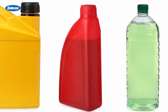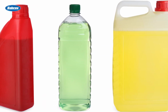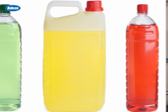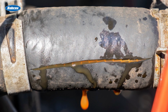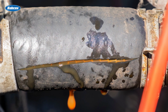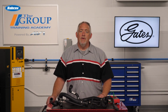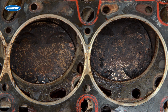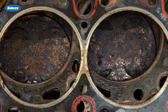Oil and other petroleum-based products are another common cause of these failures. Even EPDM rubber cannot withstand petroleum products for long because it attacks the rubber compound and softens the hose. This can occur either externally or internally by means of a contaminated coolant. An oil-contaminated hose will feel spongy, and bulges or swelling will be present. External oil leakage onto hoses should be corrected immediately, and the hoses should be replaced. If a petroleum product contaminant is found within the cooling system, such as from a failed head gasket, it too should be repaired, and all coolant hoses replaced.